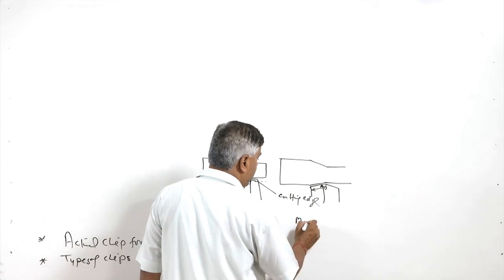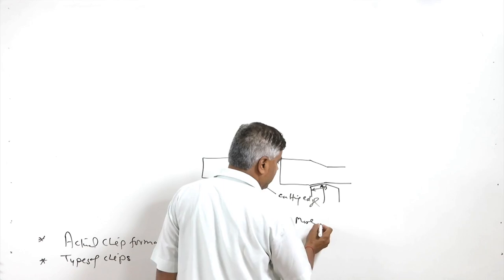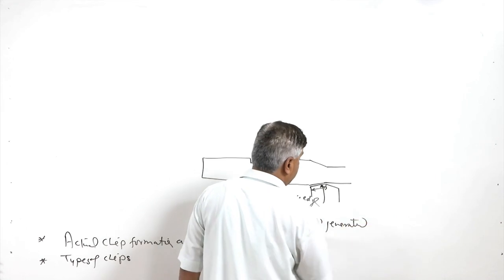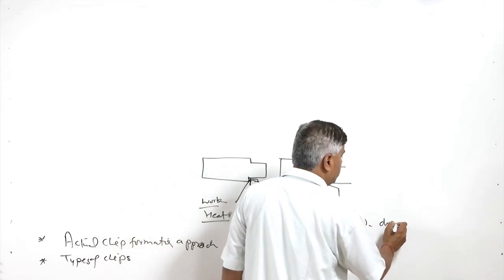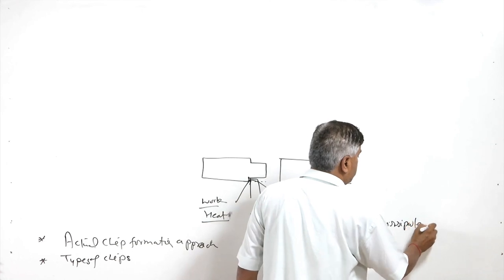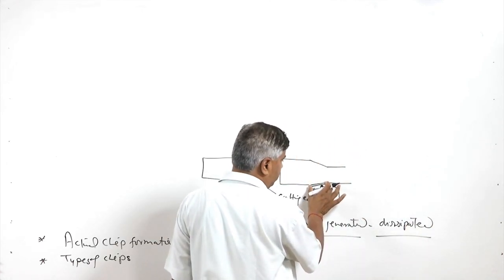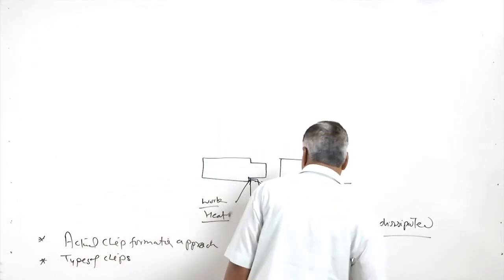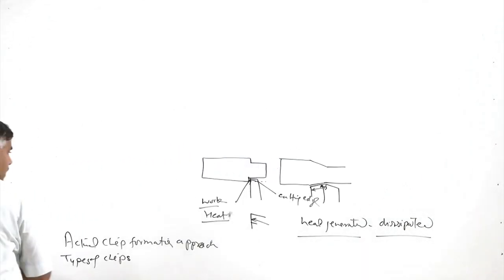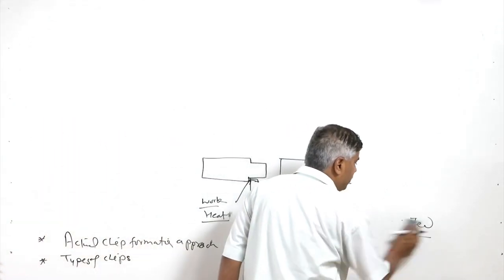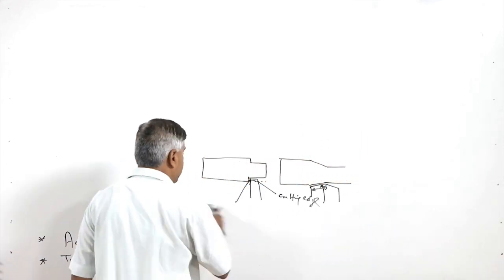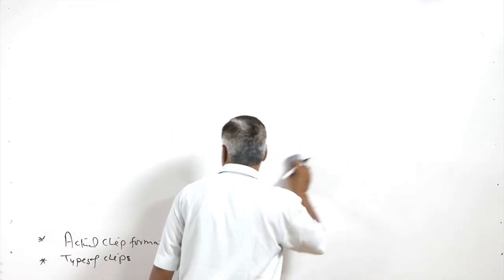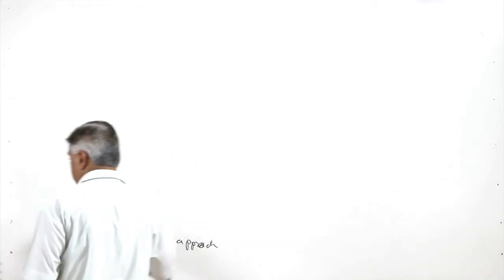While in case of oblique cutting, the heat generated will be dissipated through the larger contact length between the workpiece and the cutting edge. So, the dissipation of the heat, or heat transfer from the cutting zone to the tool, will be much faster in case of the oblique cutting as compared to the orthogonal cutting. So, the cutting edge will be at a lower temperature in oblique cutting as compared to that of the orthogonal cutting.